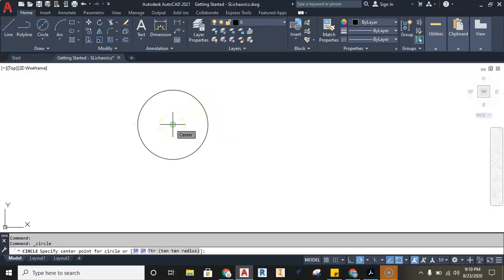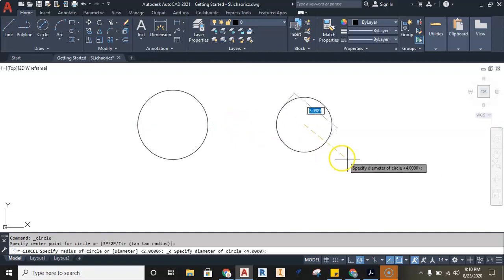And to get it to show up, you just have to mouse over the edge and then go to the center. Now, what I can do from here, if I want that first circle to line up perfectly by center, is sit over the center and then slowly move away. That's that object tracking. So if I sit over top of it, wait till it recognizes center, and then start slowly moving away. And if it doesn't seem to work, sit there again and then slowly move away. It should pick up, all right? Now, as I keep coming across, I'll just go ahead and click and then start pulling out.